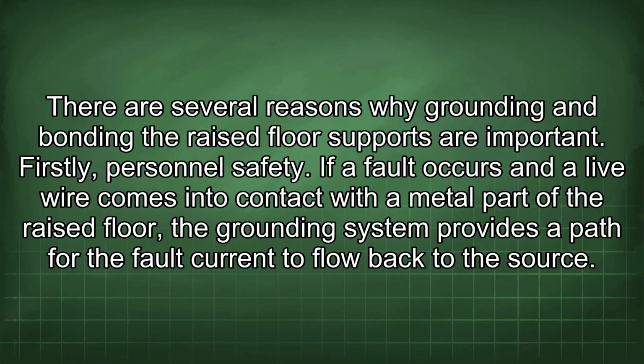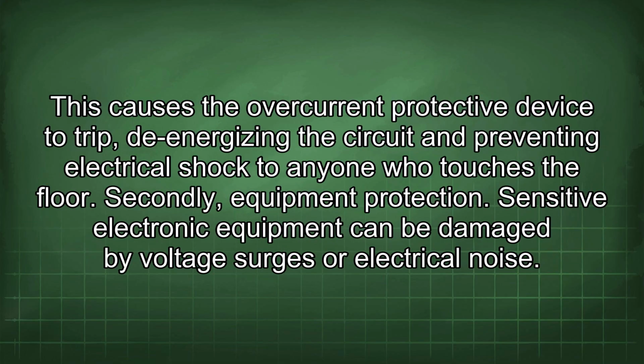There are several reasons why grounding and bonding the raised floor supports are important. Firstly, personnel safety. If a fault occurs and a live wire comes into contact with a metal part of the raised floor, the grounding system provides a path for the fault current to flow back to the source. This causes the overcurrent protective device to trip, de-energizing the circuit and preventing electrical shock to anyone who touches the floor.